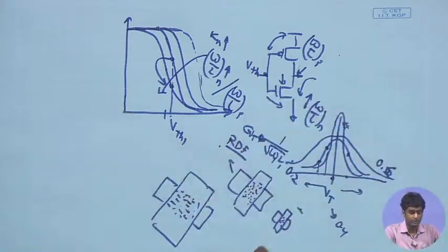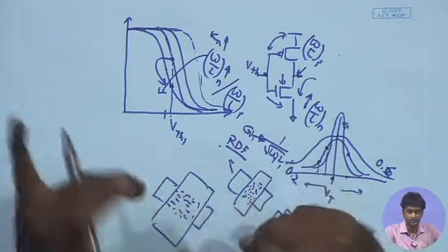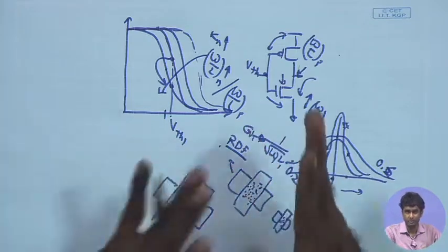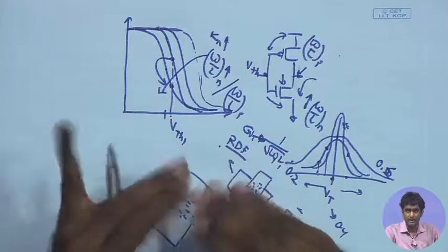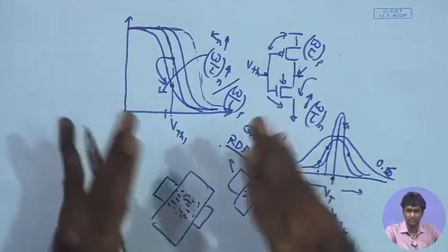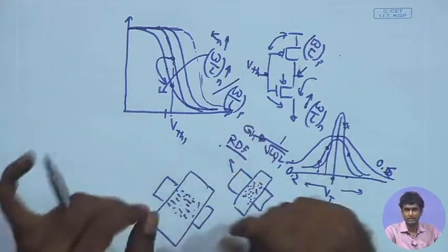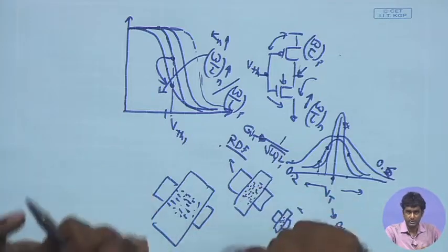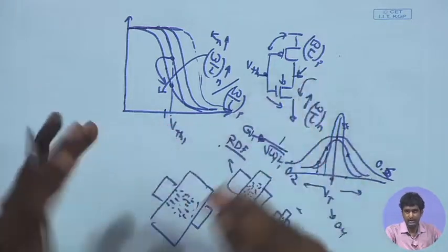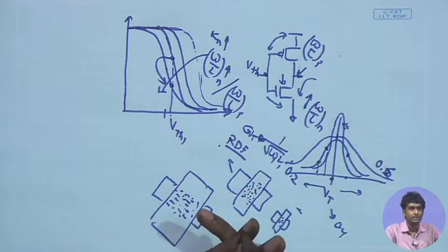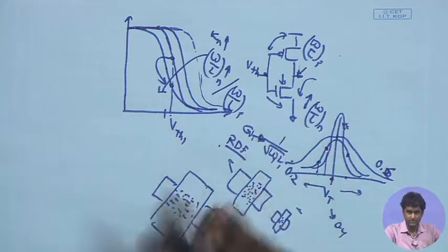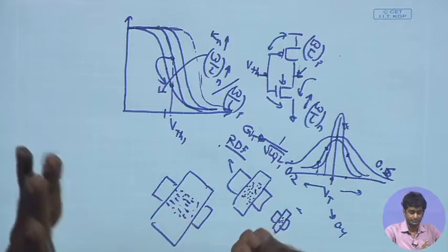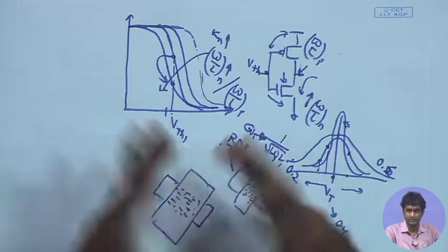So, all our differential amplifier analysis assumes that the transistor pairs are well matched, their VT, all the device parameters, lambda, everything is well matched, and that gives us a good differential amplifier. It ensures that the CMRR is large, the differential gain is large, and the common mode gain is lesser. However, we have seen in the beginning that if you have a significant mismatch between the transistors, you can have poor CMRR as well as PSRR.